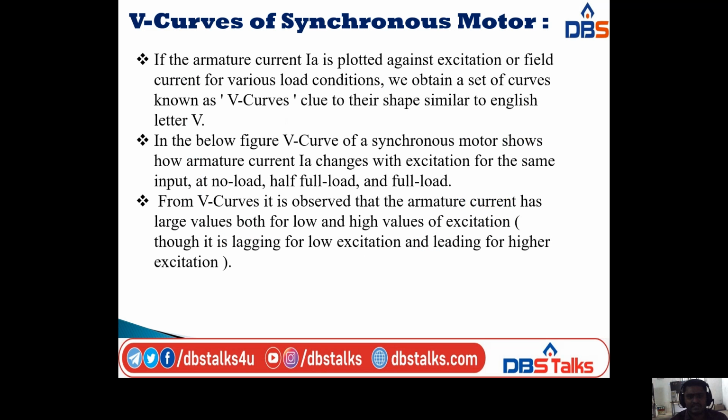So for the V curves of synchronous motor, if the armature current IA is plotted against excitation or field current for various load conditions, that is at full load, at half load, at no load, we obtain a set of curves known as V curves.